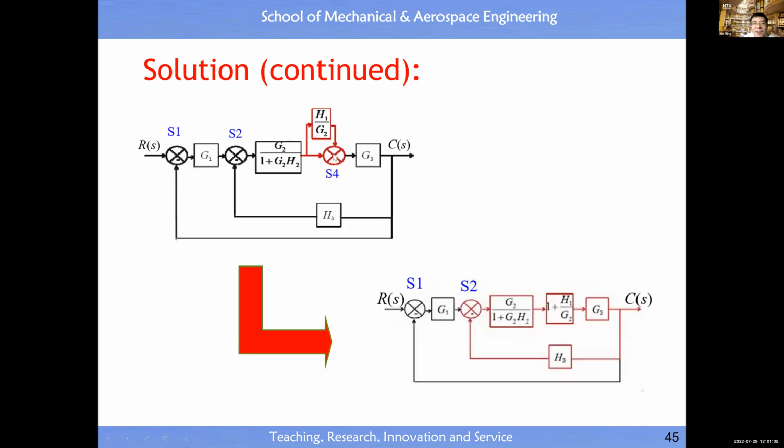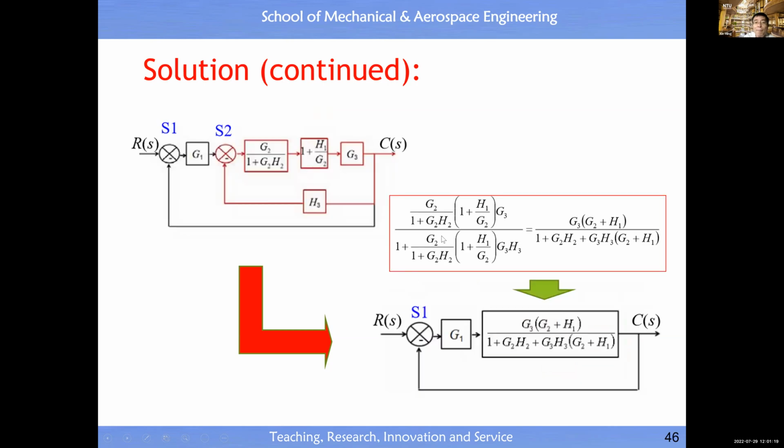So then we can easily replace this one, because here you just imagine you have a 1, because this signal passes through here and appears here. It's like times 1, so it's 1 plus this. Okay, then again, this is a standard transfer function. So replace it by the equivalent transfer function: forward branch over 1 minus loop transfer function. Then you get this one.